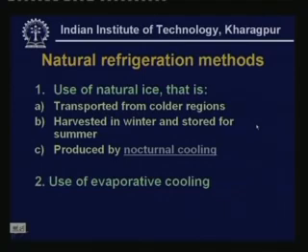Now let us look at another natural refrigeration method, that is the use of evaporative cooling. Whenever water evaporates into surrounding air, it produces a cooling effect, because evaporation is an endothermic process. This is the principle behind the cooling of water stored in earthen vessels, and also behind the cooling of human bodies on a hot day. That is how we lose heat on a hot day. However, this has its own limitations.